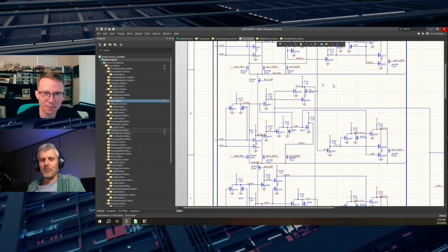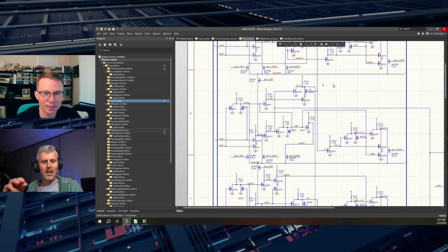So that was post Altium, right? You'd done your Altium, but you'd yet to send off the PCB. I hadn't done the layout at that point. So I had a schematic. So this is like pre-layout verification. Cool. Just trying to tie it in with the ASIC milestones as well. So you wrote your own LVS tool, essentially. Was that another Python program? Another Python program. I would share it, but it's pretty awful looking.